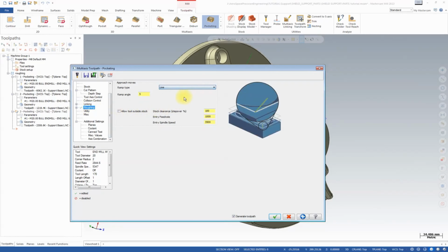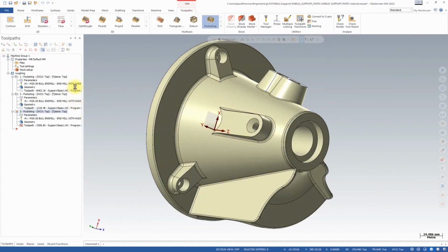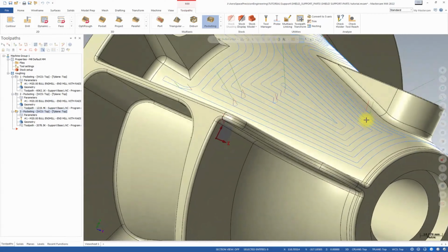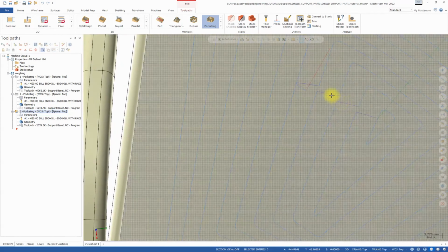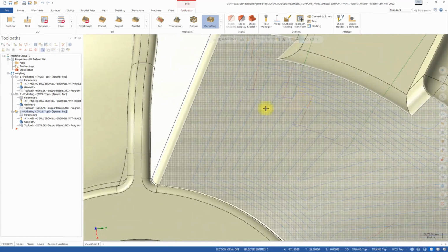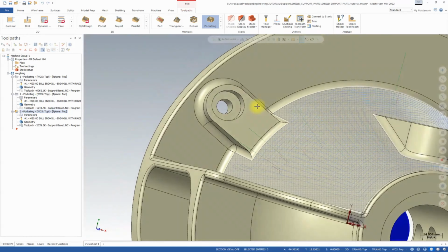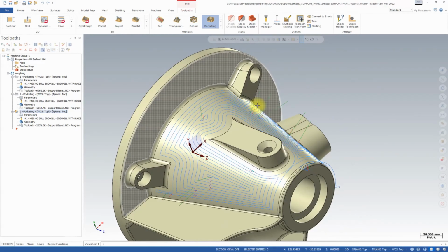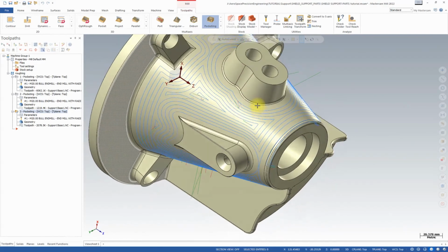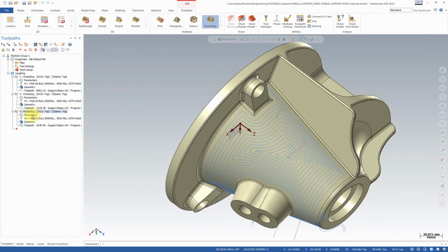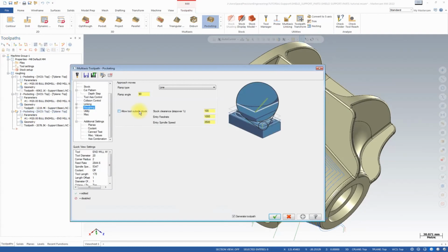Yes, I am going to approach. The ramp type is angle 19 degree, and will regenerate the toolpath. See the result. The helix entry will change, the 90 degree angle of the helical entry is relieved. The 90 degree entry motion will be the conical surface. Approach the 90 degree straight line from the conical shape.